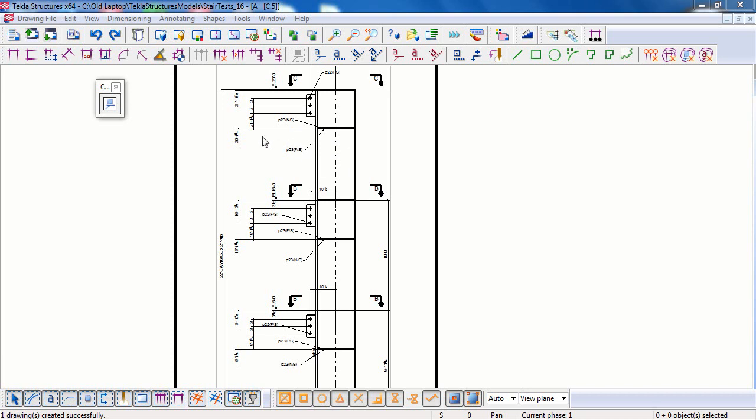What you can see here is that for these stiffeners, this near side, far side column stiffener, sometimes Tekla Structures will show two marks here, and in some cases in detailing you may just want to say, since these are all the same size stiffener, I just want to mark it once and say the quantity for the drawing. Now, there is an automatic combine marks within Tekla Structures, and sometimes it works based on a search distance that you set in the advanced options, but sometimes it doesn't quite give you exactly what you want.